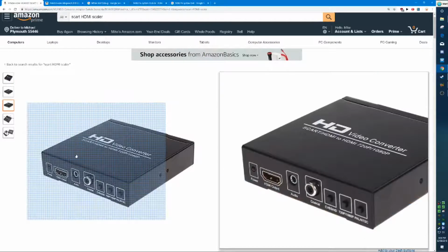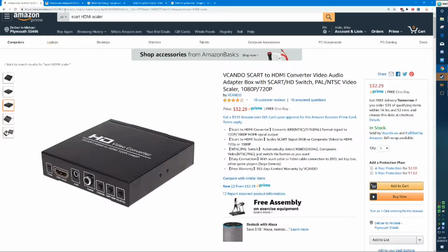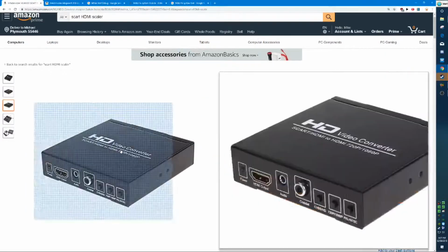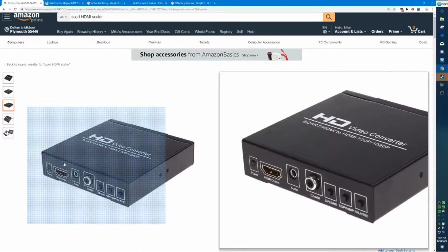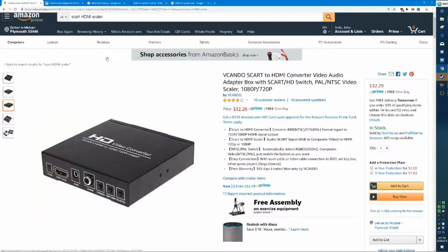So by going through one of these, because this is basically a TV scaler chip, instead of dropping the HDMI output, it'll just show a no signal message like you would see on a normal TV, instead of an LCD going black. That really helps in the Pro AV world, because no matter what happens on the input side of the switcher, you always know the output's going to be a rock solid 720p or 1080p or 1080i output.